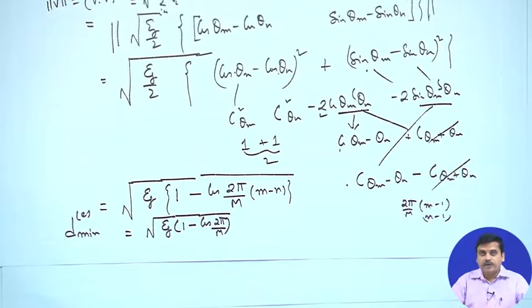So, till this point we have covered two important modulation techniques. That is the pulse amplitude modulation, where you are selecting an amplitude based on the bit sequence. The number of bits you would group together to select an amplitude would depend upon the number of amplitude levels.